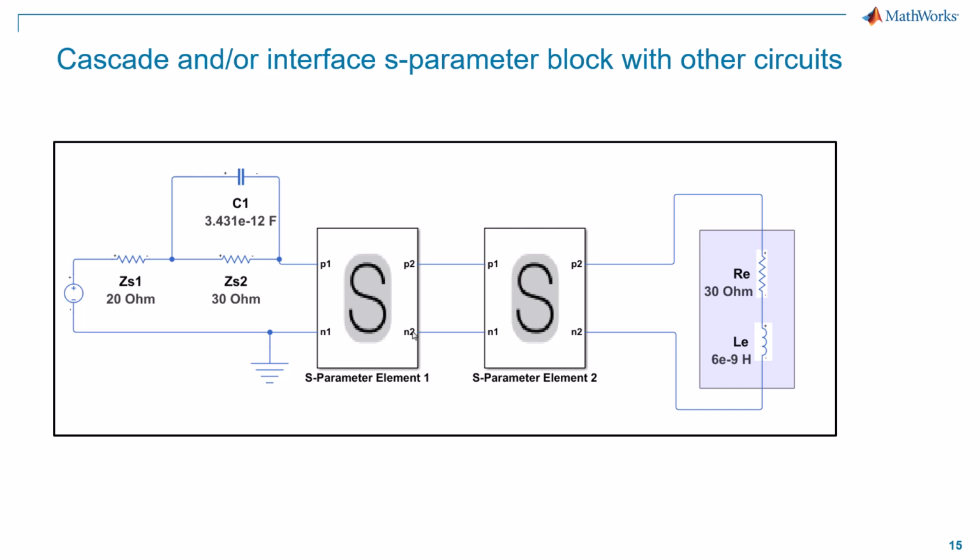And of course, the ultimate goal, the motivating circumstance for bringing S-parameters in, is most likely to model S-parameters as a part of a larger system where you may cascade S-parameters, or you will likely connect them to other circuit elements. Perhaps you've got some type of equalization on a channel you would like to try, so analog equalization circuits connected to your channel that you could simulate now as one larger system in Simulink.